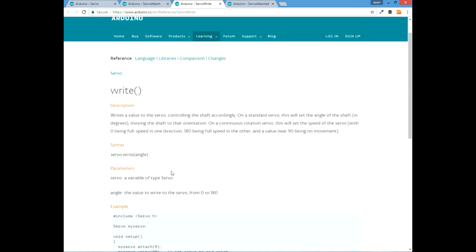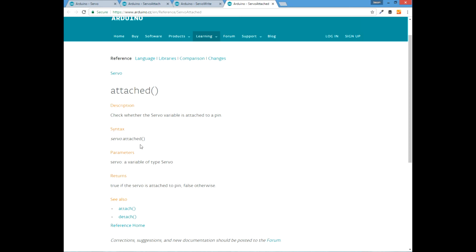But again, back to the library, this is a simple way. Now that we've included this library, we only have to write 2 more lines of code and we can instantly control a servo. And we don't have to worry about all the other code that's involved in actually translating that command into the correct voltages that are going to get the motor to do what you want.